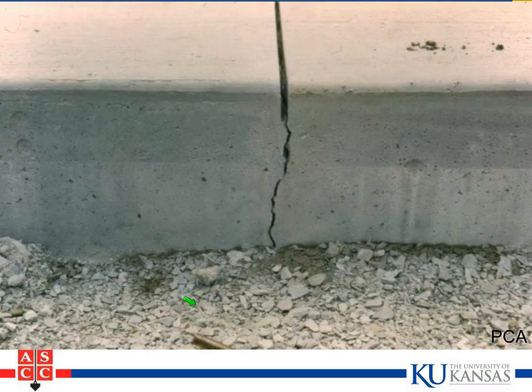Here's a slab where they did not cut 1/4, but in this case it turned out to be weak enough to get the weakened plane formed there, and we got the crack. To the owner, this is not cracked concrete. It's nice and straight. Also we can fill this joint up to protect it from getting dirt and dust in there. But this is not cracked concrete.